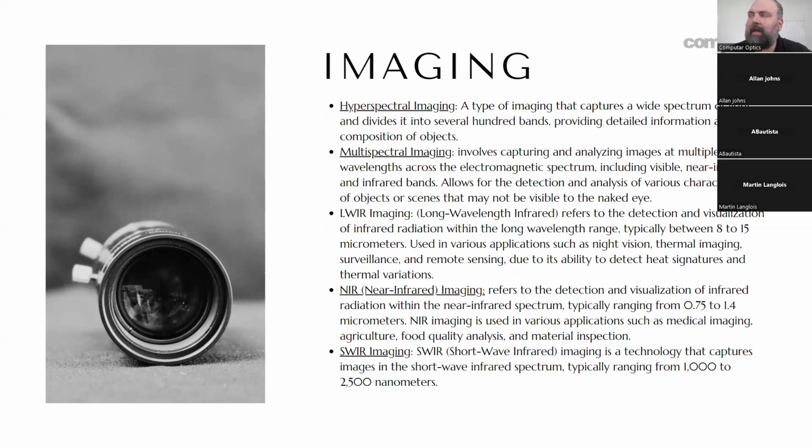But first, let's talk about hyperspectral imaging. Hyperspectral imaging and multispectral imaging, these are terms that get thrown around. And for someone like me that has dyslexia, I will have issues remembering which one is which. But the main difference between the two is the number of spectral bands the cameras cover. So hyperspectral imaging systems acquire images in over 100 contiguous spectral bands, while multispectral imaging, they're taking a few narrow bands and they're comparing those narrow bands in the software that they're using.